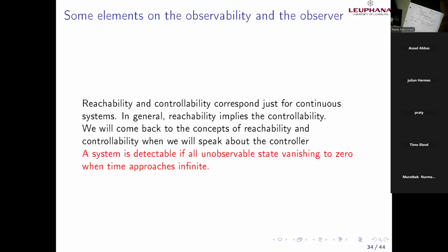If I have an example in MATLAB, I will try to show you a little bit better, but we can also understand with words. In this case, if a part of the system is unobservable, if I have some state which I cannot observe, as a result, I cannot place all eigenvalues.